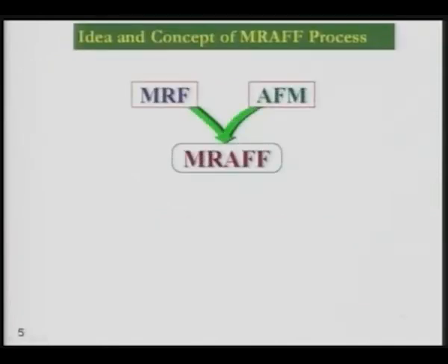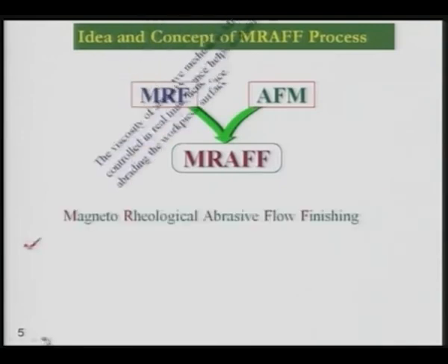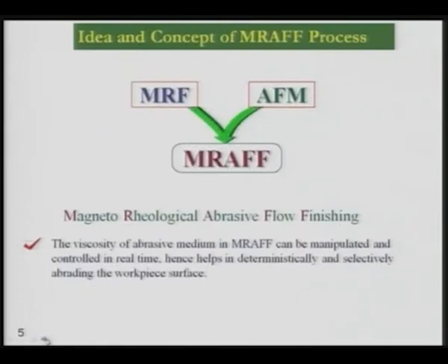So the MRAFF process, magneto-rheological abrasive flow finishing process, is the combination of magneto-rheological finishing and abrasive flow machining process. The viscosity of the abrasive medium in the MRAFF process can be manipulated and controlled in real time. Hence it helps in deterministically and selectively abrading the workpiece surface.